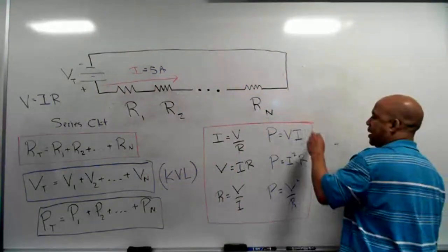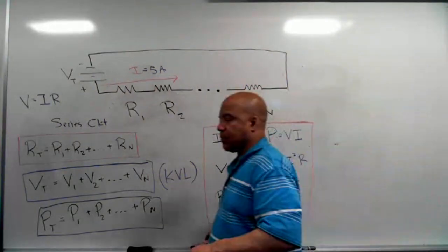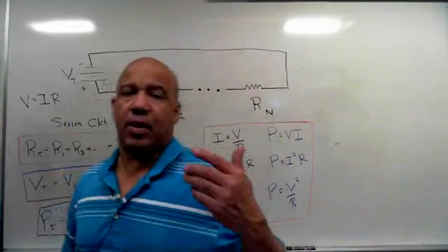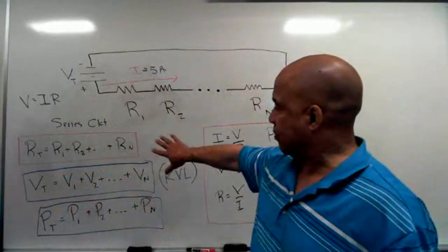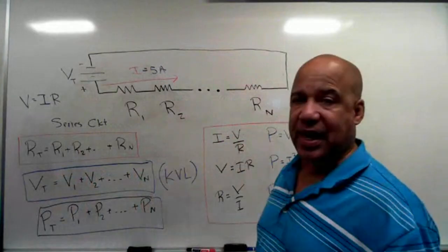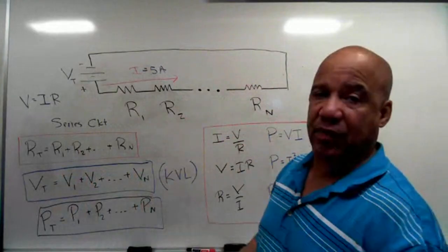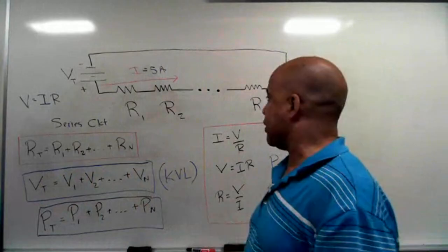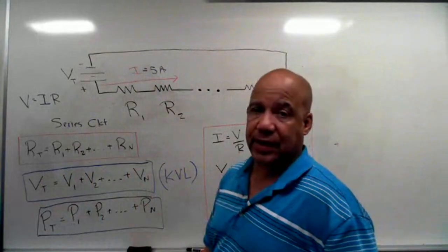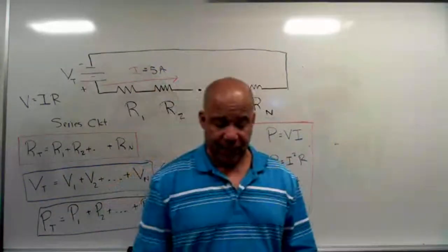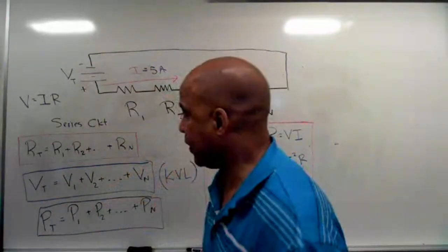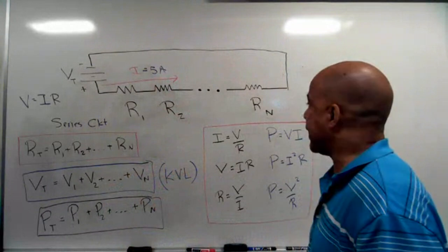And the only thing to remember about a series circuit, the current in a series circuit is the same everywhere. So with this set of equations and understanding that the current is the same everywhere in the series circuit, in theory, you should be able to solve any kind of series circuit. So what I want to do is practice solving series circuits. So that's what we're going to do next.